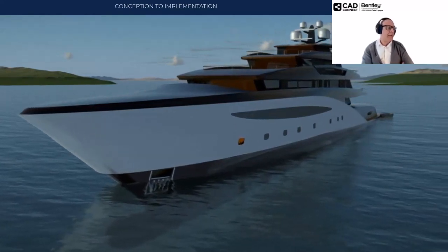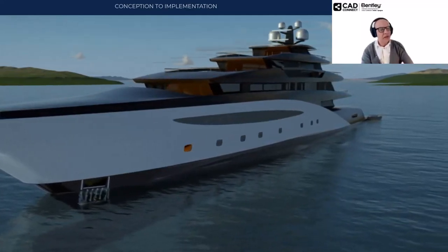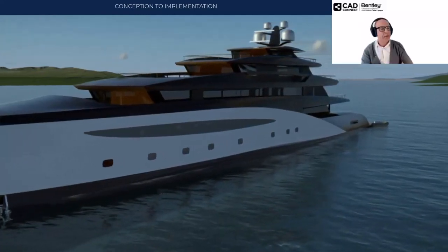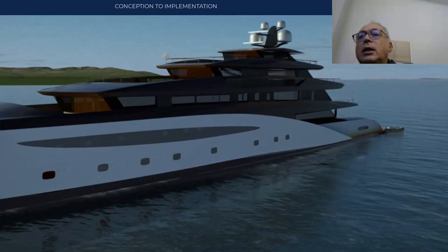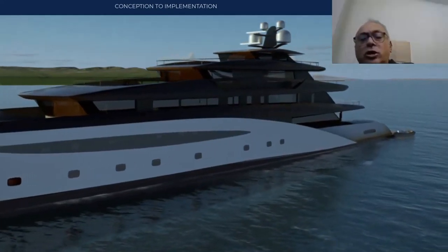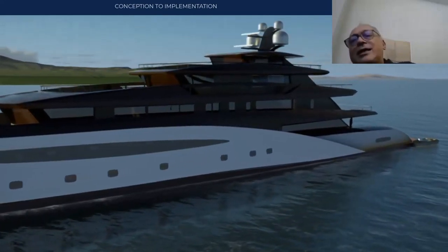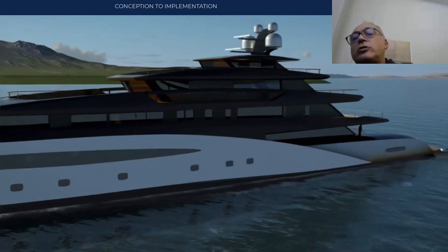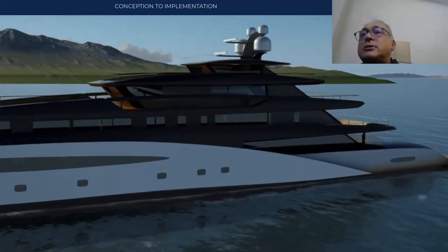What specific aspect of production do you deal with? The structural hull, the exterior finishes, the interiors, the systems, the propulsion? We do the modeling of the structural part, so everything that is the structure of both the hull, therefore the submerged part, and the superstructure. What material is the structure of a yacht made of? The structure of a yacht is essentially made of two materials. High strength steel for the hull, sometimes also common steels and light alloy for the superstructures. Then there can also be hulls completely made of light alloy. We have done a lot of them.